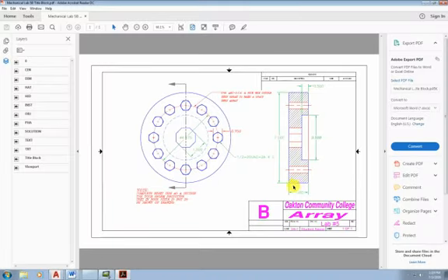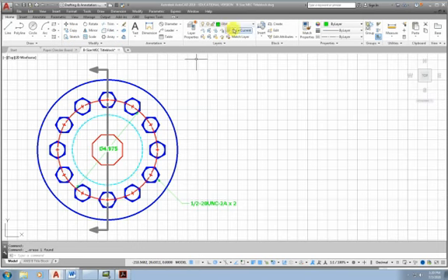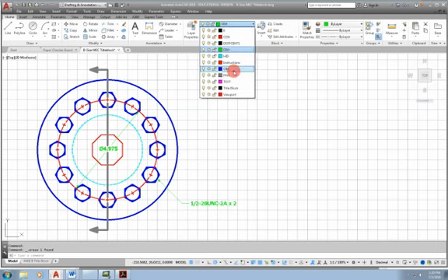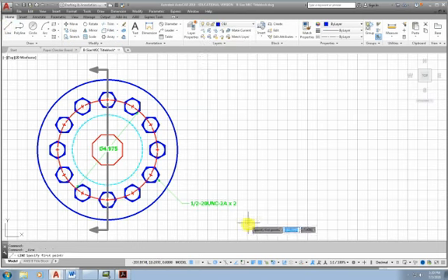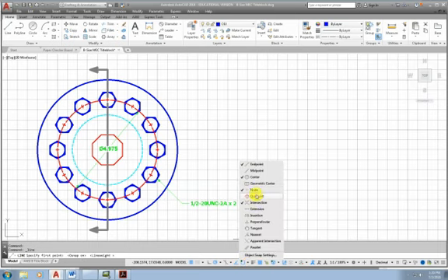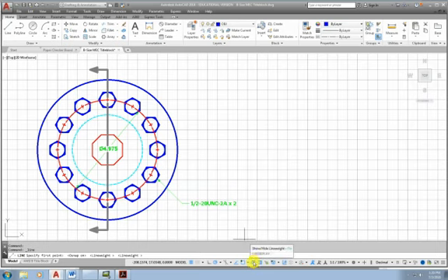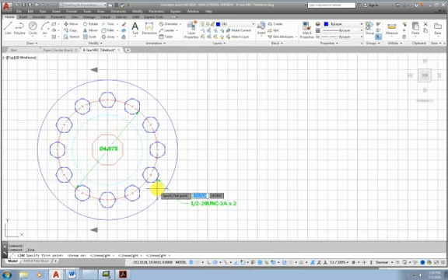Alright, we're going to draw the side view of it, and so we'll look at this drawing, and what it's basically saying is it's 1.5 inches by 7. I'll come back to the drawing, and I'll project over those lines. I'm going to make the object line active. I'm going to select line, and in my O snaps, I'm going to select quadrant. So I'm going to enable quadrant, and I think I turned off my line weight, so I'm going to enable my line weight.